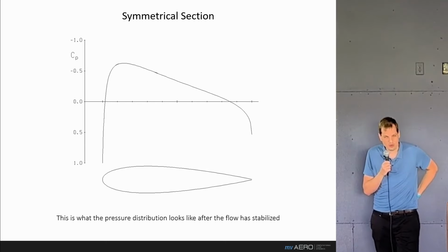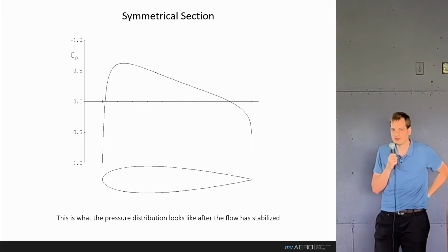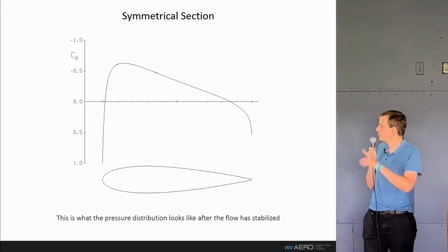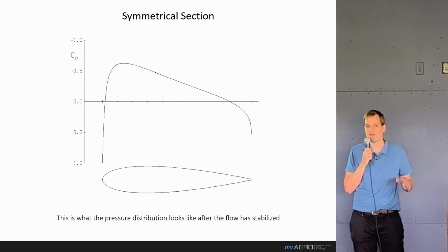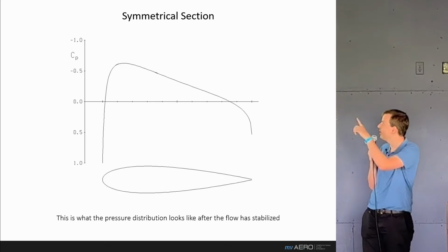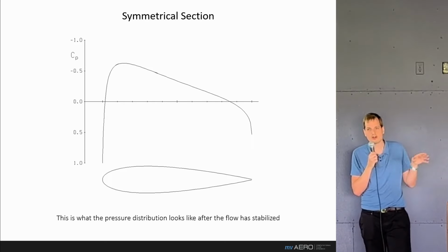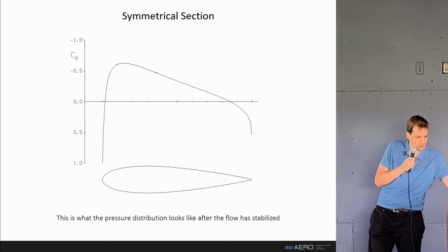So what we've just seen, we're now plotting in 2D, and we're looking at a surface pressure gradient over that exact airfoil. As we can tell here, we have stagnation pressure at the leading edge, and from there on air speeds up all the way to the apex of the pressure distribution, after which it will encounter more and more pressure until it slows down.